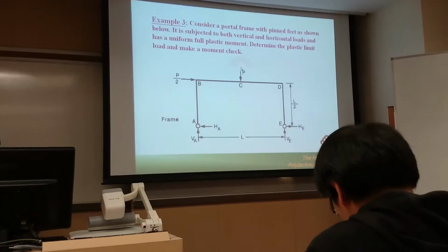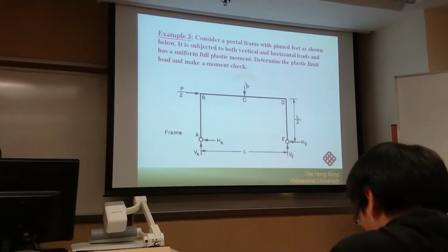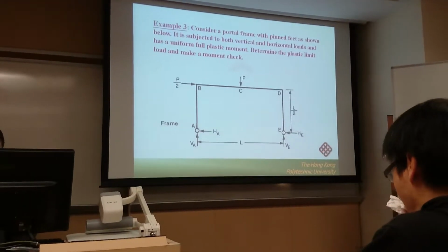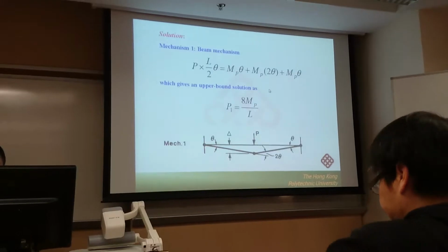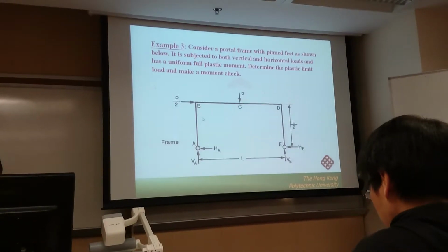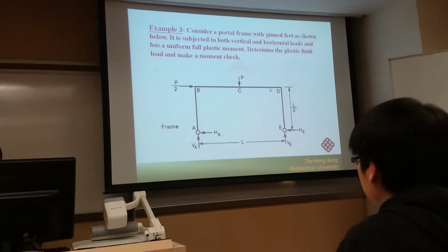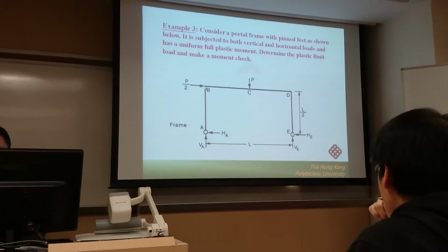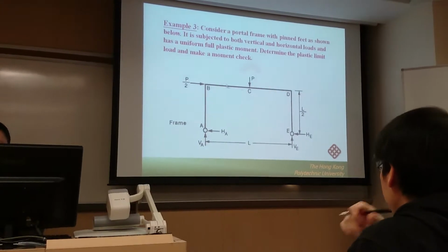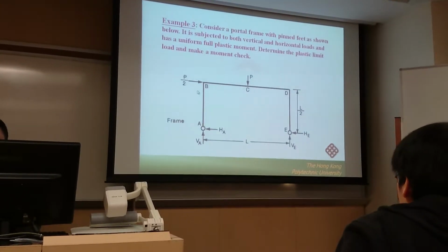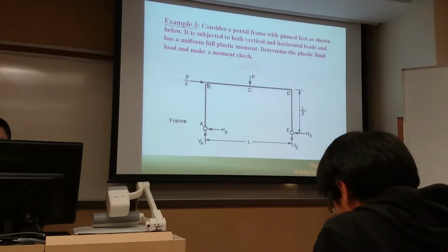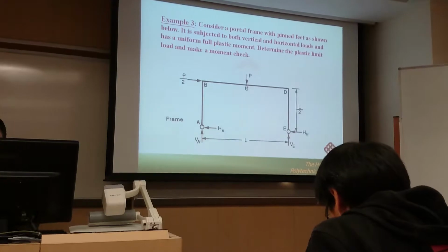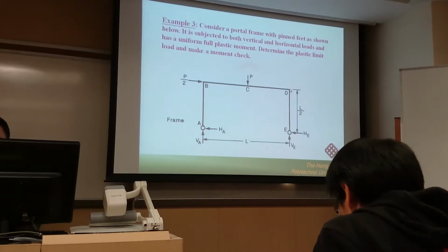Example 3. In this example, we assume the plastic hinge. We don't know the location of the plastic hinge for the real collapse case, but we can determine 3 possible plastic hinge locations. One is at point B, because this is a connection; for point C, this is a force application location; and for point D, this is a connection.